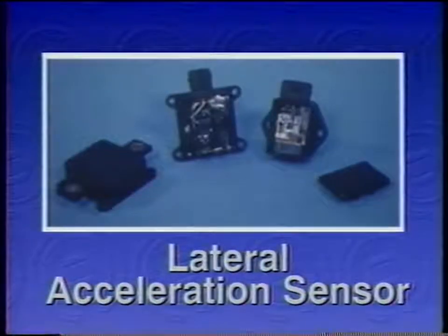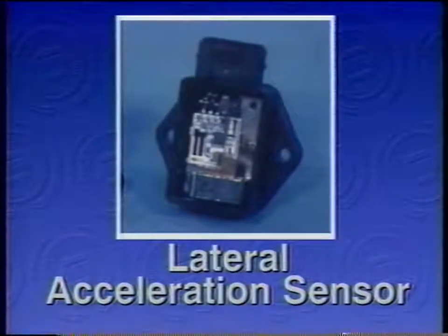The Bosch 2S Micro is equipped with a lateral acceleration sensor rather than a switch as in previous Corvette applications. The sensor permits a graduated reading of progressively higher side loads. The switch simply opened and closed when side loads of over 0.6 Gs were encountered.